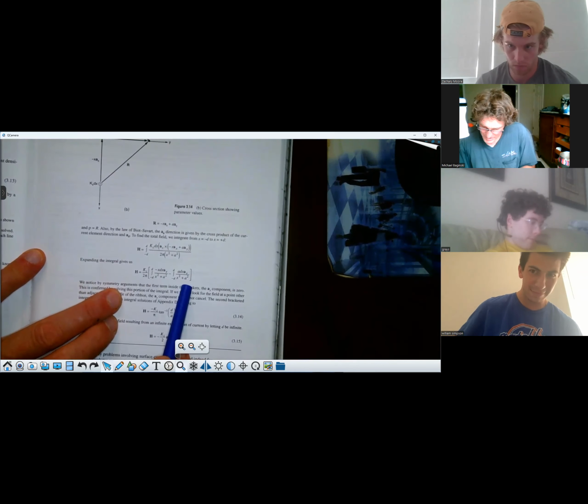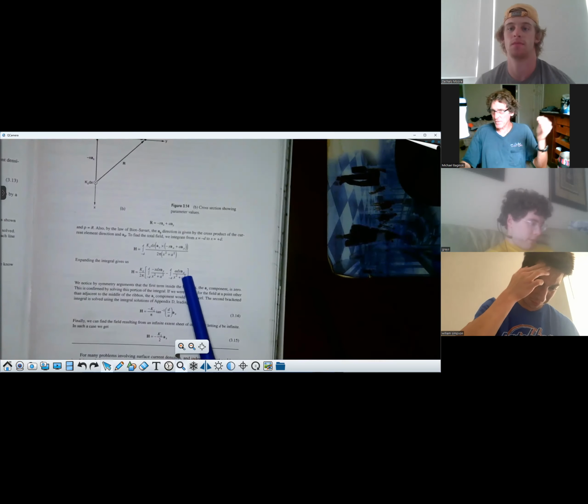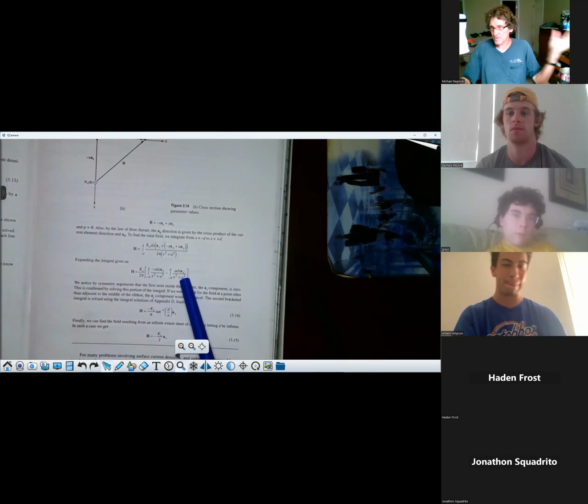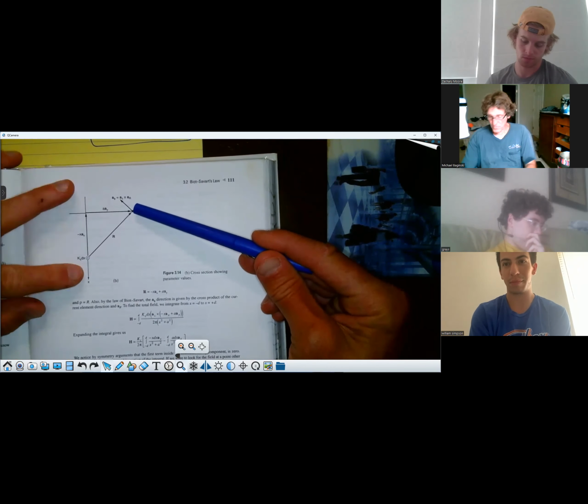Now, something I'm going to mention about this. I hope you can see this. I know it's not exact, but can you all follow me on why I'm doing what I'm doing? I can do this on the board for you. If you just look at this, it'll make perfect sense. Once you get the differential H field from this current in the Z direction, you integrate it over the actual width of the ribbon.